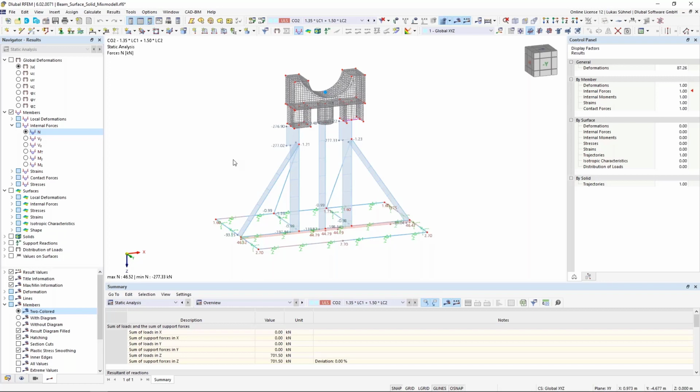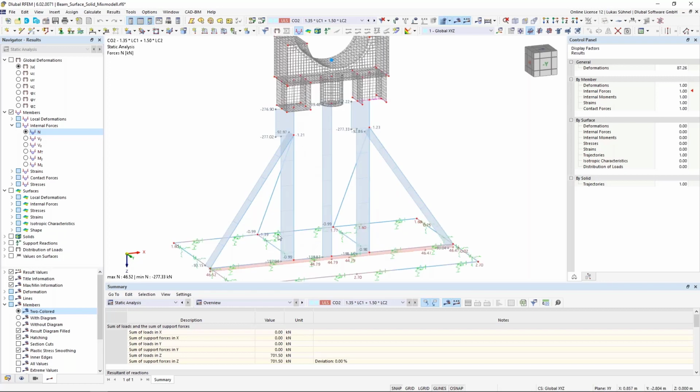The formula basically is you take the axial force in a member and divide it by the critical force of the member. If that is smaller than 0.04, then you don't have to run a buckling check for the member. If we switch it around, if the critical force of a member divided by the existing force is bigger than 25, then buckling is not an issue. And this is a value we can check via a specific add-on.